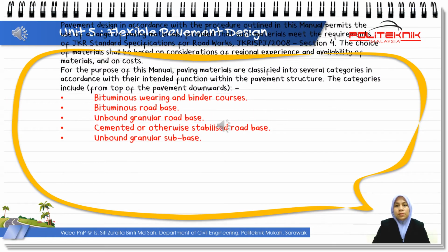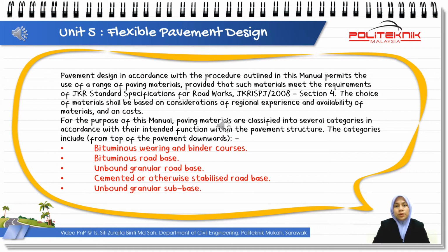Pavement design in accordance with the procedure outlined in this manual permits the use of a range of paving materials, provided that such materials meet the requirements of the JKR Standard Specification for Roadwork, JKR/SPJ/2008, Section 4.